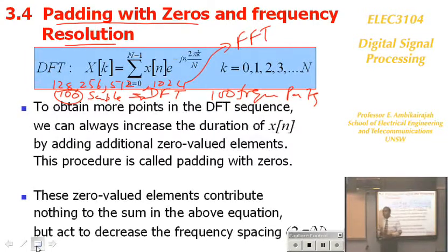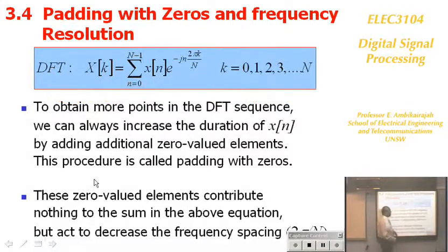So if you want to apply FFT, you must have a power of 2 number of samples. But what happens in real signals? Say you sample the real signal coming out, and you got 1,000 samples, but you're short of 24 because the signal only comes for a short time. You sample them fast, and that's it. You don't have another 24.